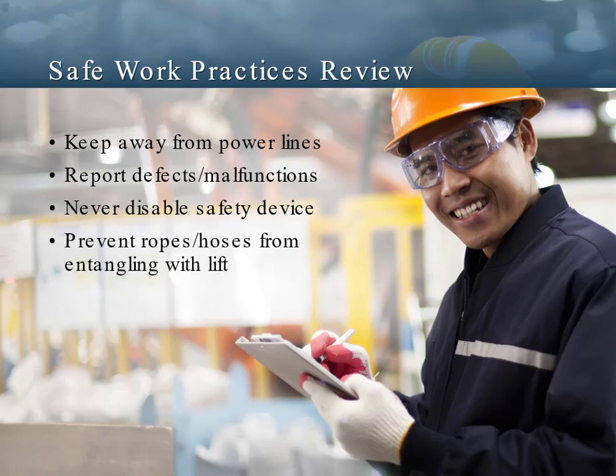Prevent ropes, electric cords, and hoses from entangling with the lift when the platform is elevated, lowered, or moved. Before lowering the lift, make sure the area under the lift is clear of tools, debris, or personnel working on the ground. And of course, never engage in any stunt driving or horseplay when working in or around aerial lifts.